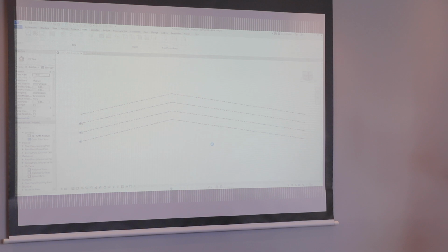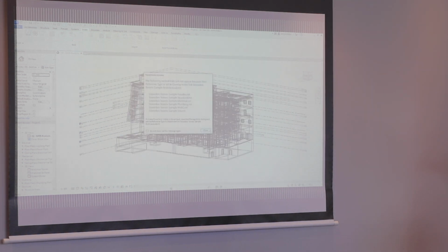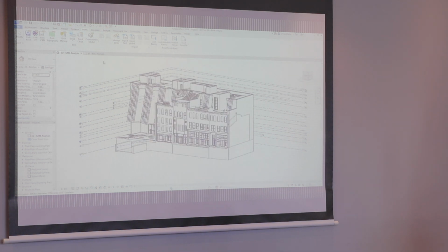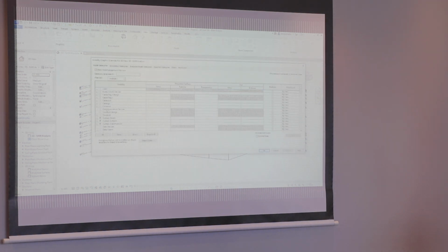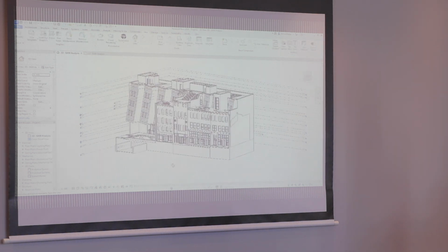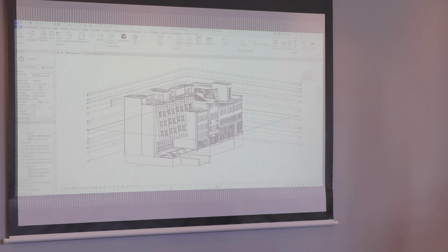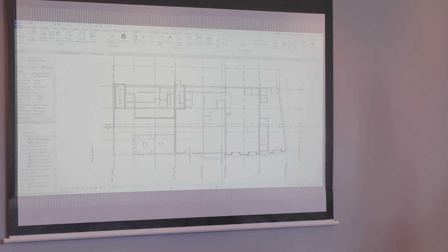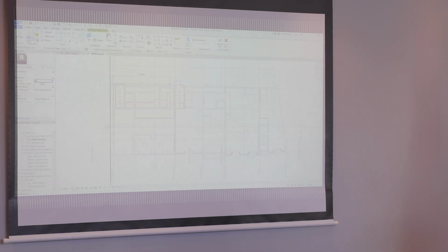And I just get left with this view, which is basically your skin, right? So we have a building, we have these floors that are roofs, we have walls with no U values, etc. So what's a really quick way to do that? Well, using the conceptual massing, I can just literally draw a box around it, right? Draw a mass, create the heights and the different spaces from that.